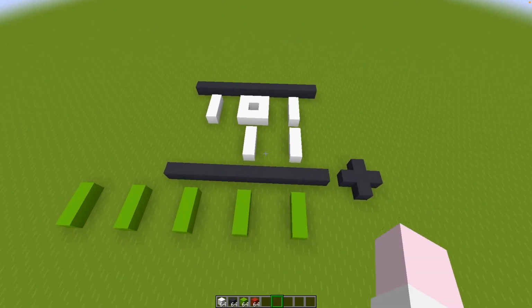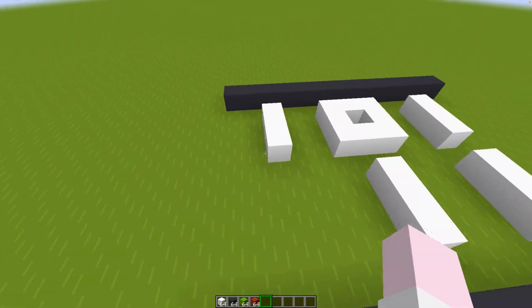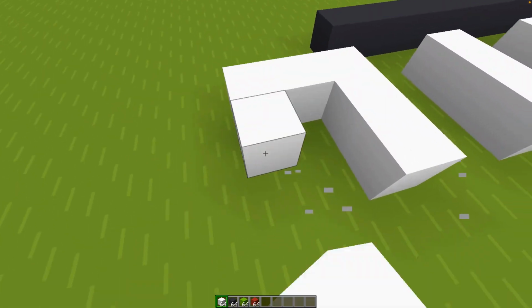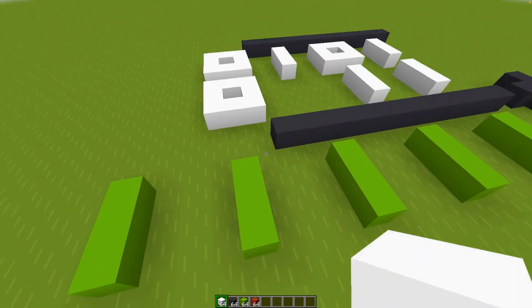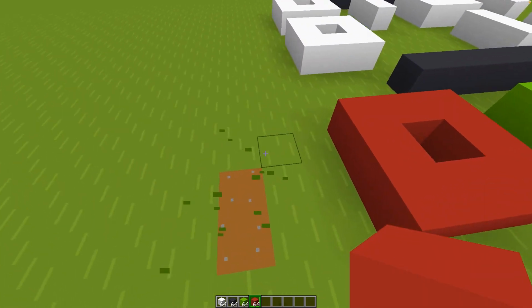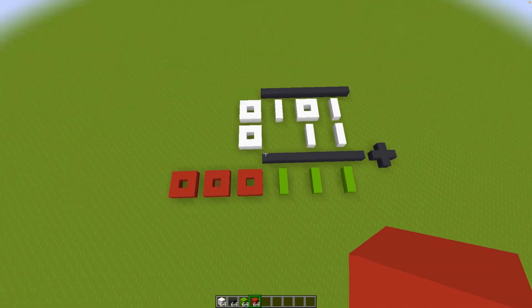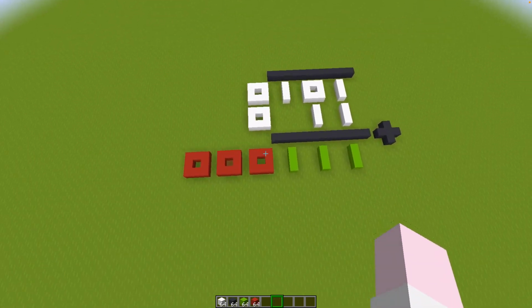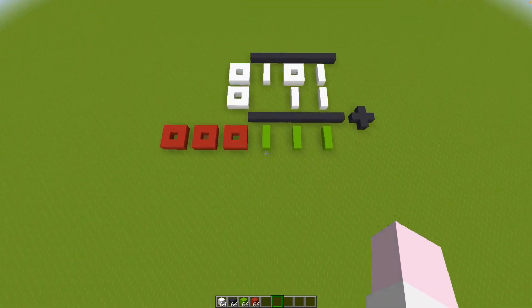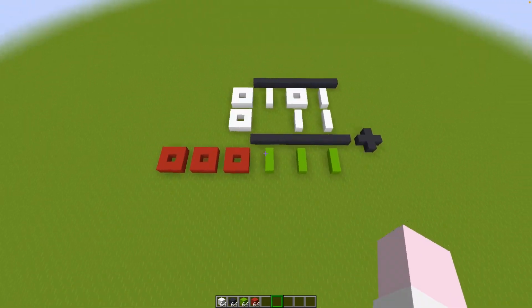However, we need to do one more thing. If the OR of these two digits is 0, for example, right over here, if we OR these two, that's going to be a 0. So we cancel this propagate, which in turn makes everything a 0 again. And this will go on forever. And that's our carry line. So if both of them are a 0, then the carry becomes a 0 and everything after that. However, if both of them are a 1, then we go with a 1,